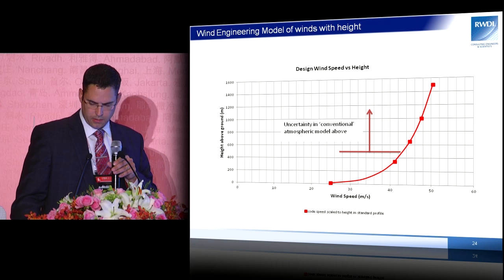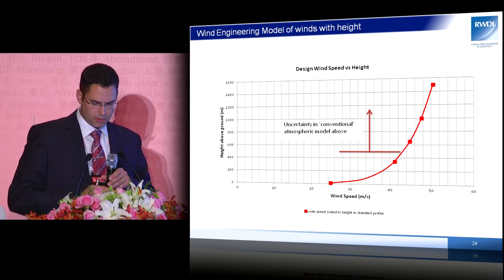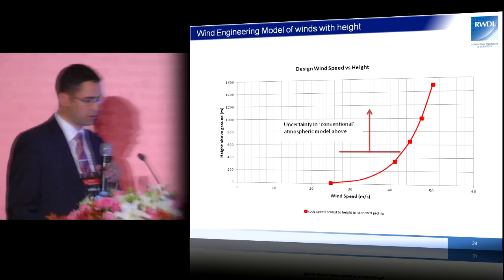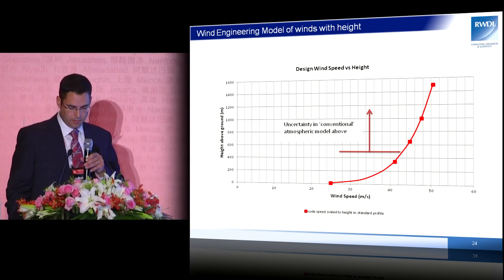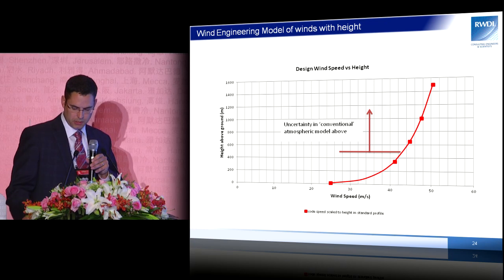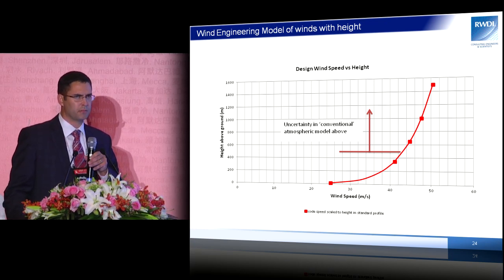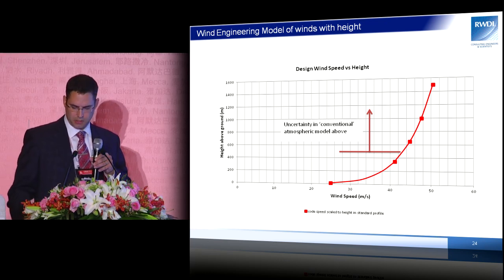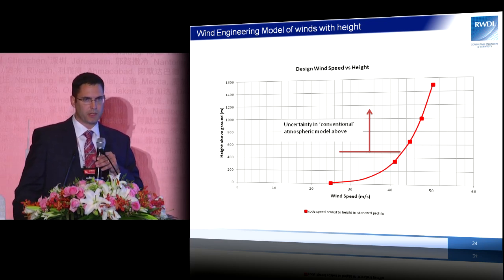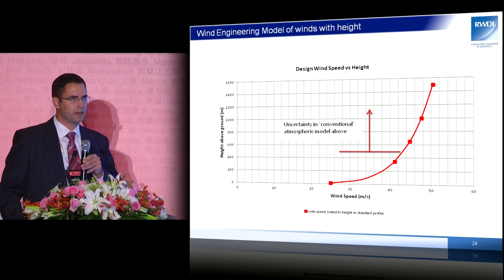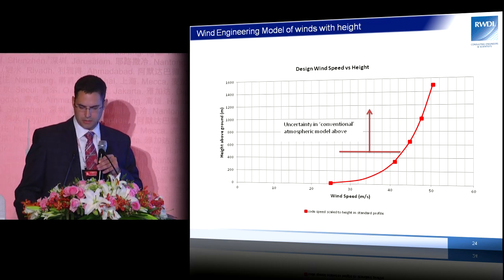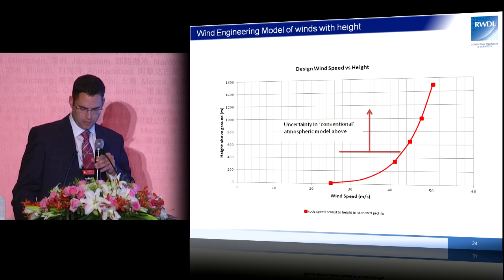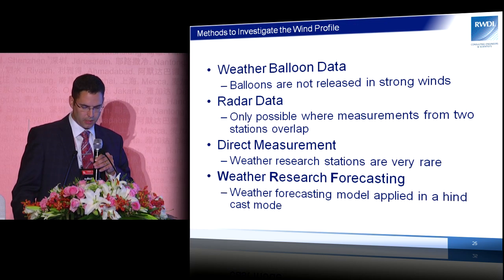So beyond that, if we look at uncertainty in those profiles, I showed the different profiles associated with different storms, and the methods that have been developed are certainly quite well established for buildings. I've put 500 meters here, some would say 300 meters, but certainly for the building heights that we are contemplating today, I think it's worthwhile to try to get an understanding of what the actual profile is for the particular region that we're working in.